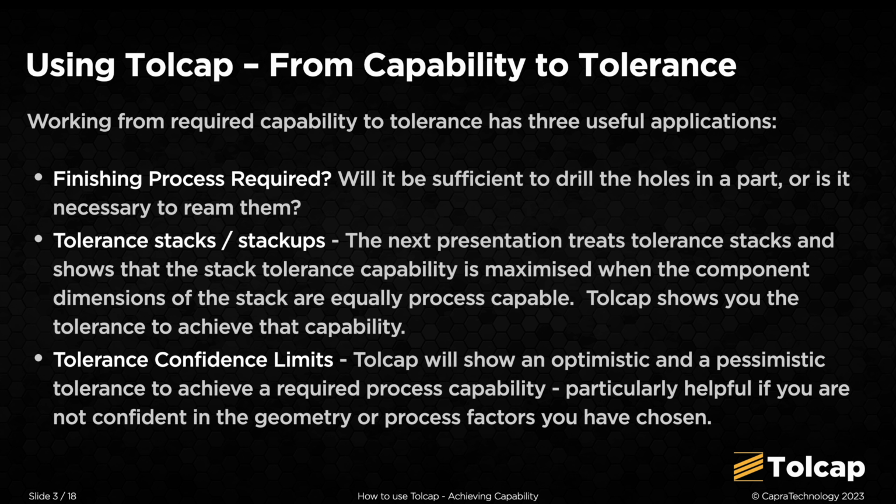Working from required capability to tolerance has three useful applications. Firstly, is the final process, and by the way we always look at the final process that determines the dimension of interest, is the final process good enough to achieve the required tolerance capably? Do you need to ream those holes, or will simply drilling be perfectly adequate?